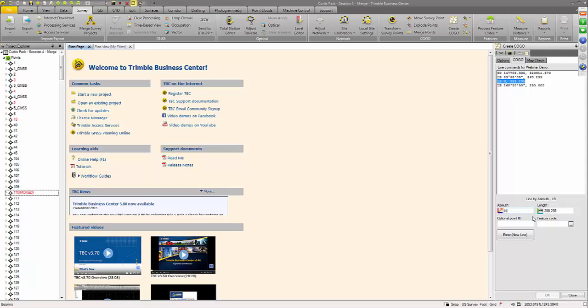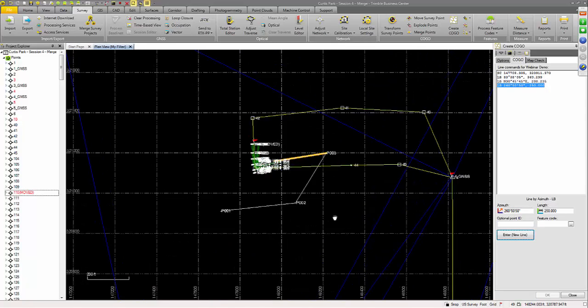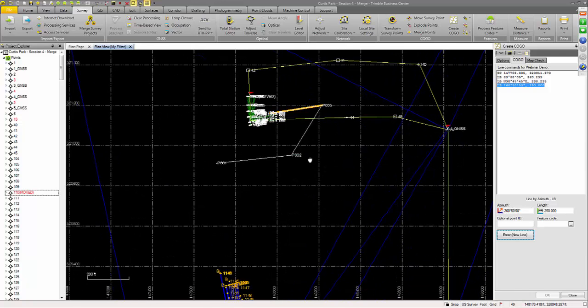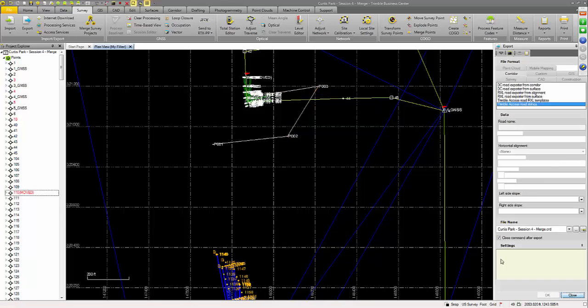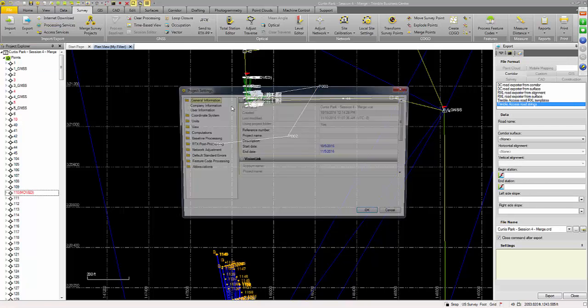Let's say north 30, 45, east. And it should take it. And yeah, you can see I've completely jacked around my drawing there. So just because it says azimuth, you can still enter in a bearing, and it'll take it. But the display units is the big one.